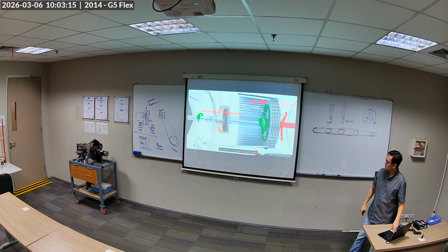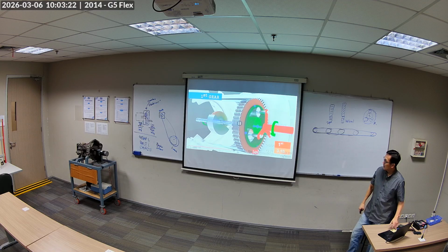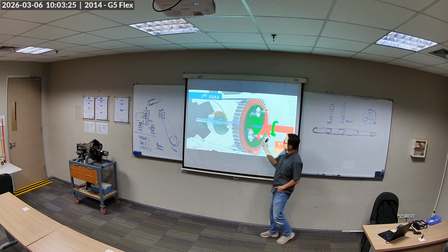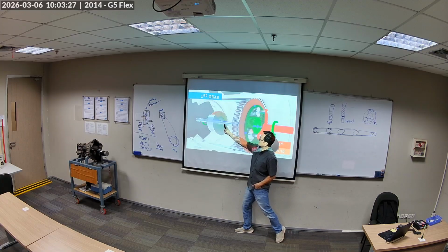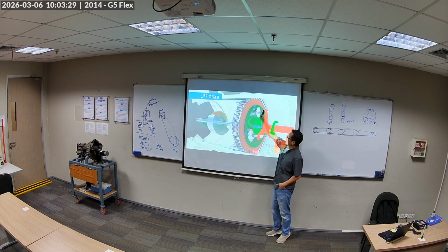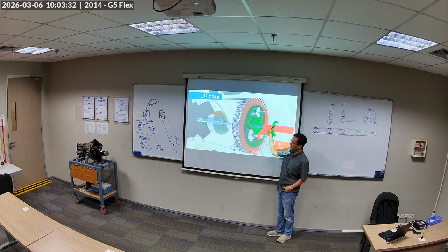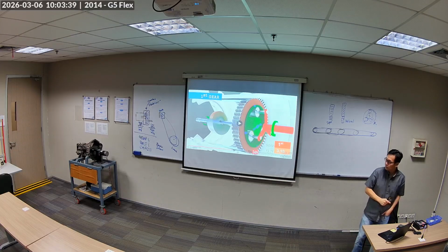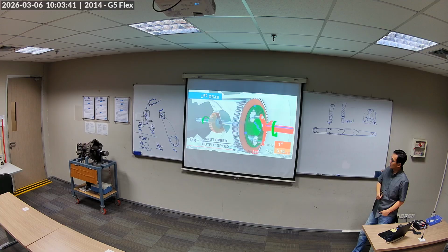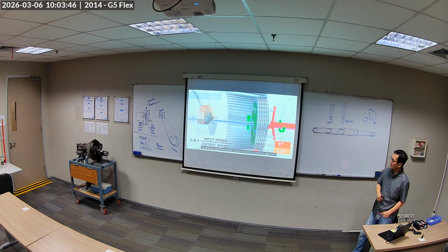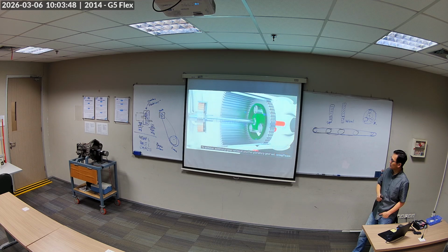Since the ring gear is stationary, the output shaft will rotate as shown with almost 1/3 of the input speed. Okay? So ring gear is locked. Sun gear is the input. The planets are connected together with this red piece. It's called the planet carrier. And so we have that ratio. To achieve additional gear ratios, add another planetary gear set.